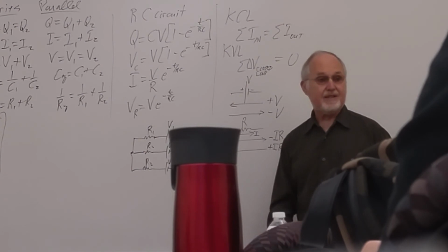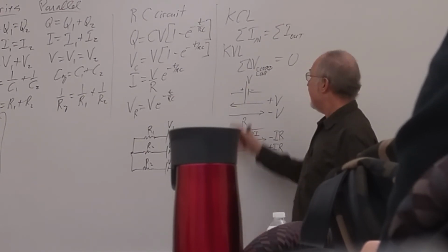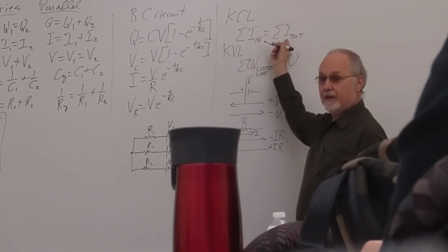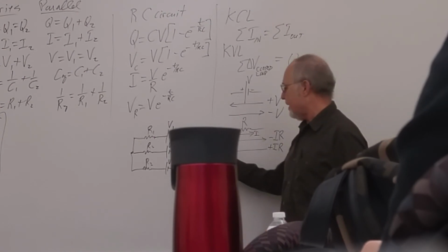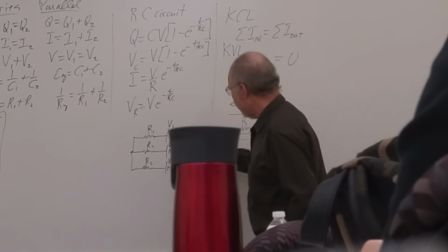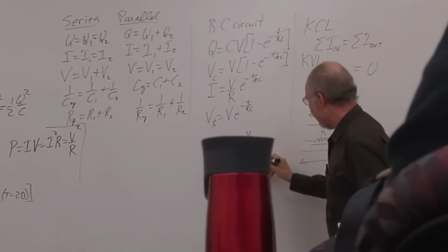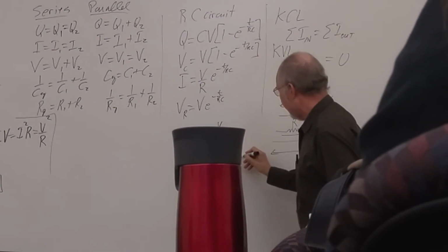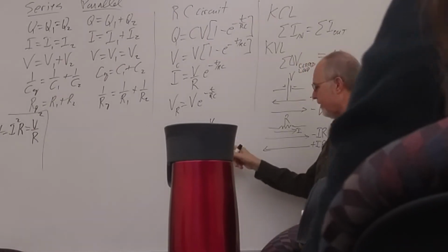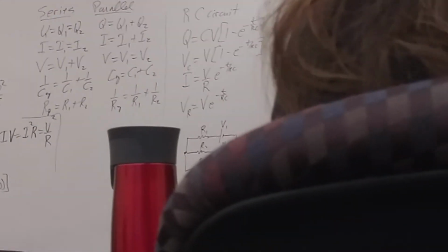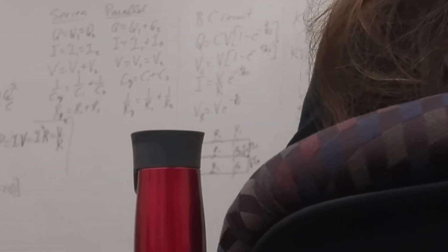If I give you this, I can tell you which point to pick. And you write currents going in equals currents coming out. So maybe you had current 1 going this way, current 2 going that way, and then current 3 this way. And so KCL at this point would be I2 equals I1 plus I3. That's the way I've got it drawn.